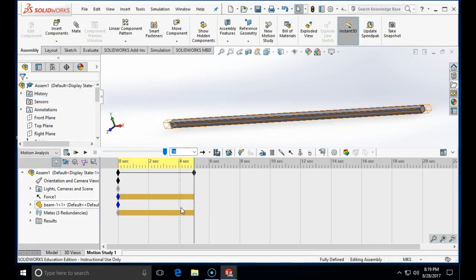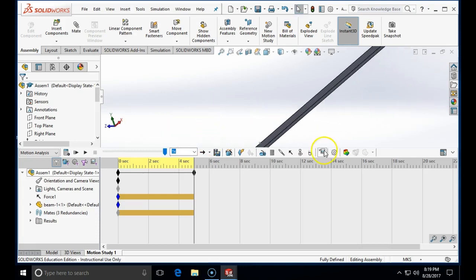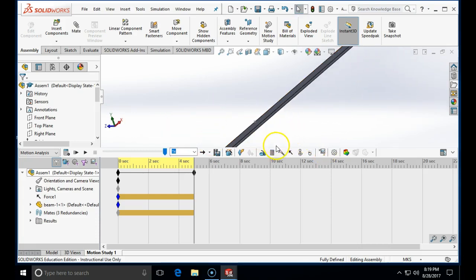Okay. So essentially, if we are setting up a beam, or if we are setting up something that have multiple supports, we need to be careful not to choose the entire face as a support, but only to choose idealized vertices or edges that we use. Otherwise, it will not work.